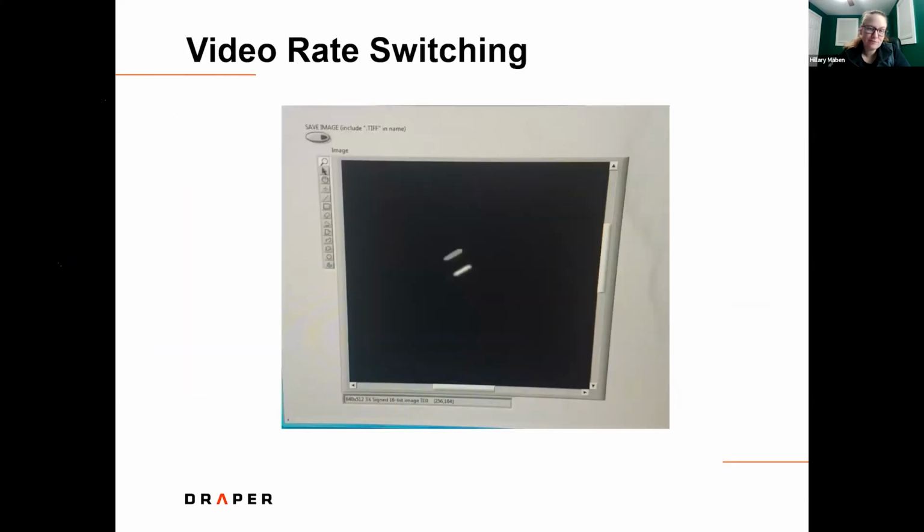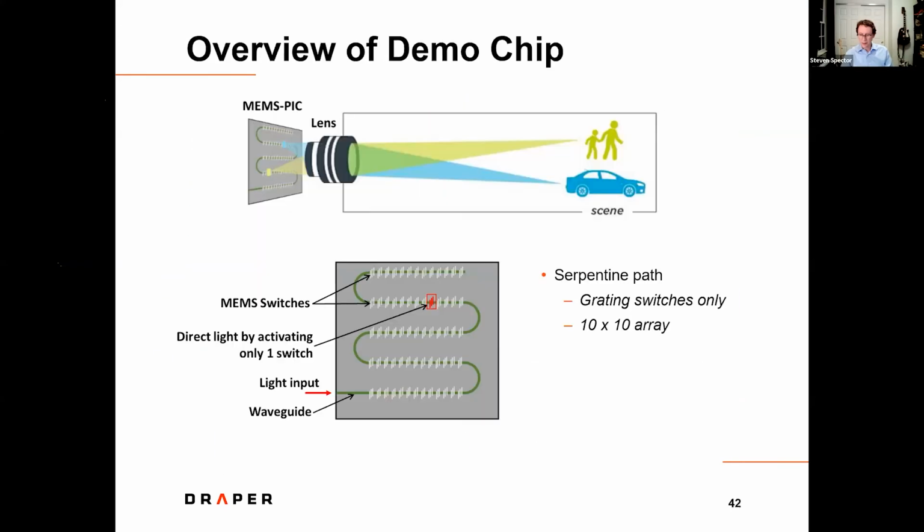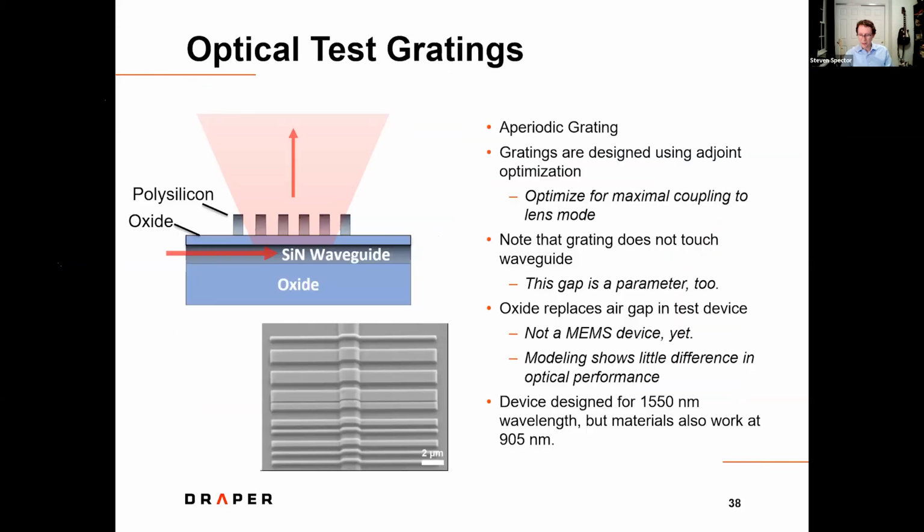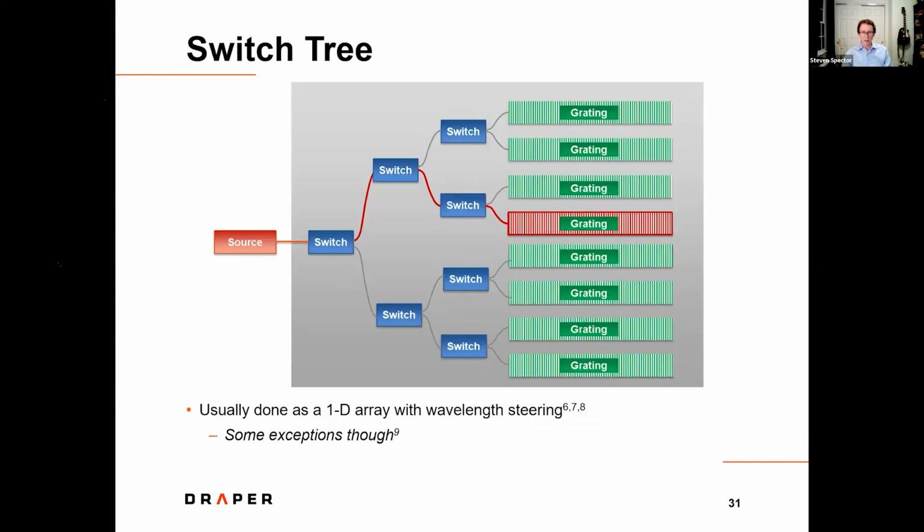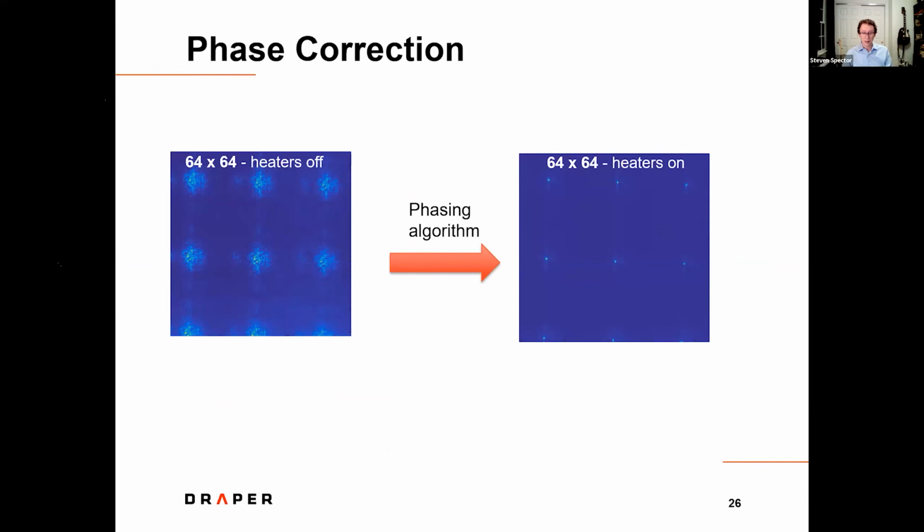Yeah, I'll go back, although I think I could probably do it without it. So heaters provide the phase shift, but you're probably asking about the algorithm. It was a hill climbing algorithm, where you basically go up and down with each heater. Is this result better? Nope. Okay, I'll go the other direction. Is that one better? Nope. And just basically go through them all that way.